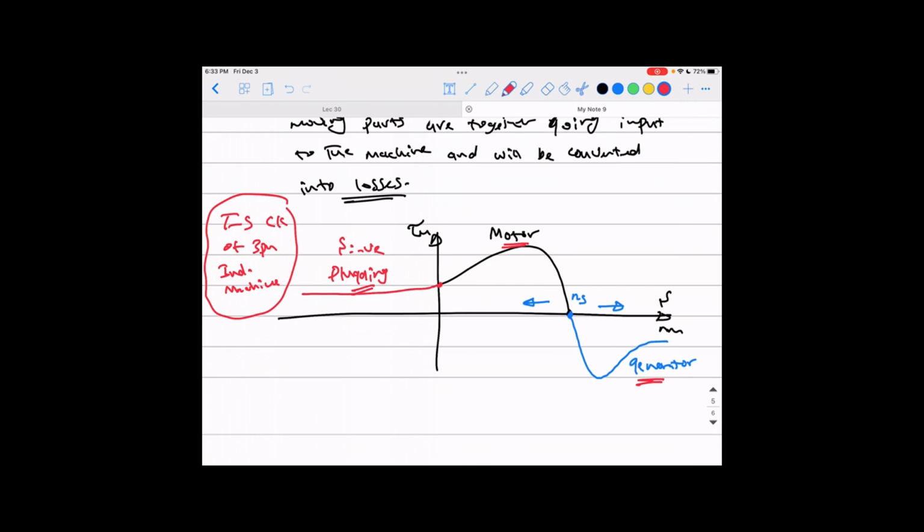And we talked then about the starting of the three-phase induction motor, which is the way of reducing the high amount of current drawn by the motor at the starting instant. We talked about the different methods of doing this, emphasizing the two most important ones, which are soft starters using power electronic converters, and the Y delta starter, which is the most commonly used one.